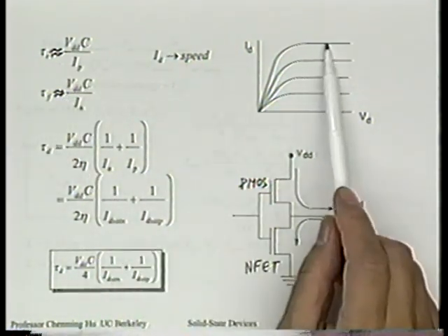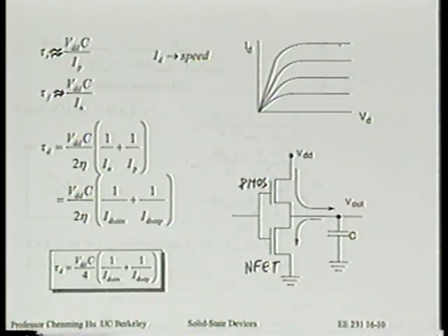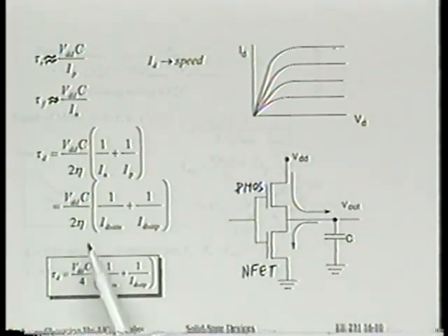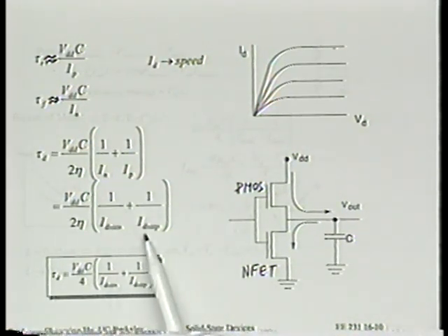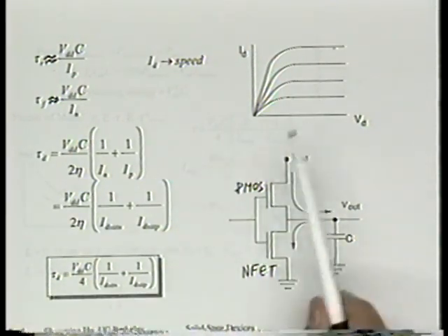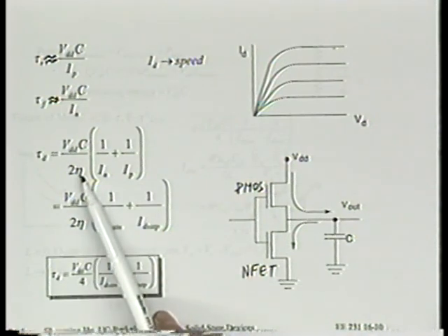Do we take it here? Do we take it here? Do we take some kind of average? Average is probably an easy way to answer. But how do we average that? It's too complicated. So instead of average, we're going to force them to be ID set: ID set of the N-channel transistor and ID set of the P-channel transistor. If we do that, certainly we cannot force this eta to be 1, right? So we put this as an unknown.